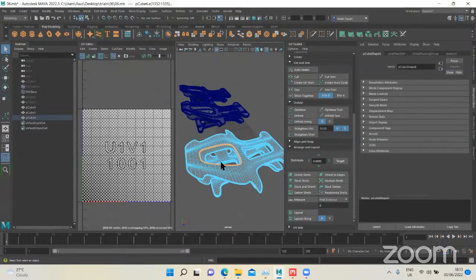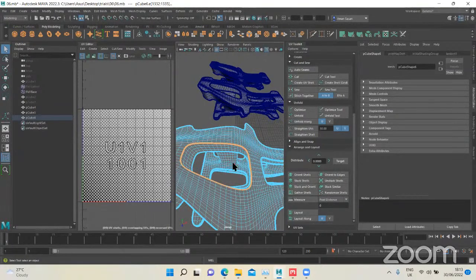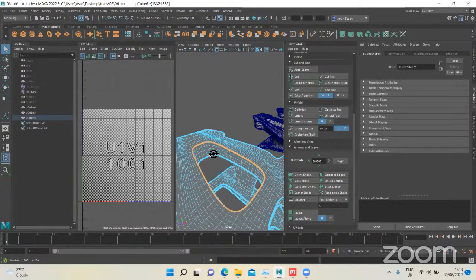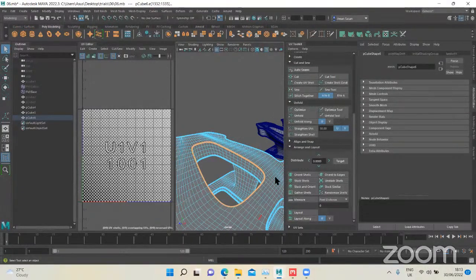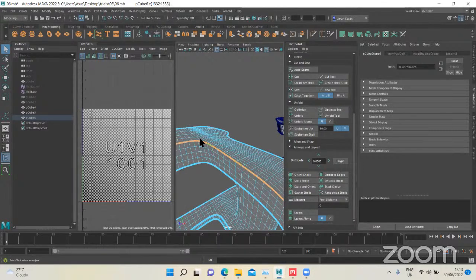So you can keep doing that for all your edges. Why I'm cutting over here is because, let me first of all explain why we cut the models. We need a seam in our models. For example, if I'm texturing this whole thing, there's always going to be a cut where the texture sort of breaks. It's like how a cube has 6 sides.